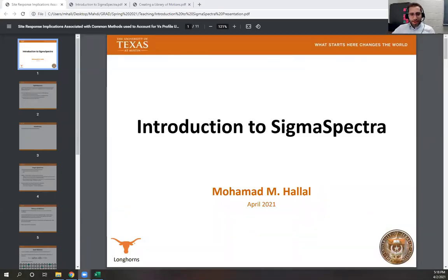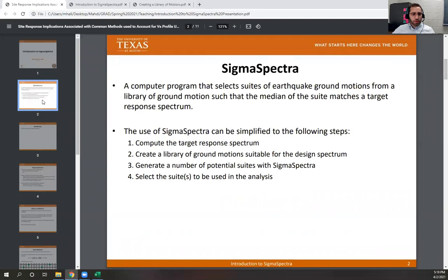Hello everyone, my name is Mohammed, and in this presentation I will demonstrate to you how to use SigmaSpectra in your project. So in your project, you will be using SigmaSpectra to select a suite of earthquake ground motions that fit on average your target response spectrum. And once you have this suite of ground motions, you will use them as an input to your 1D site response analyses. The use of SigmaSpectra can be simplified into the following steps.